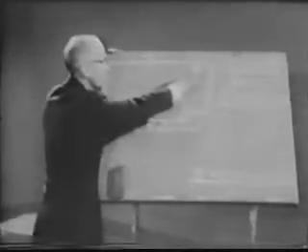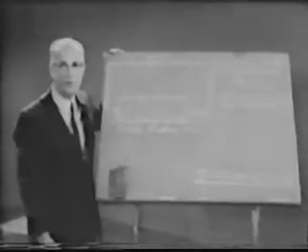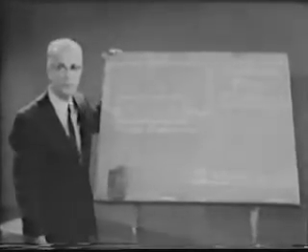The sample of germanium, which I have mounted, is quite similar to one which Bill Shockley and I used in an experiment at Bell Telephone Laboratories in 1949. The experiment demonstrated vividly, for the first time, the importance of minority carriers in semiconductors and their principal dynamical features, namely drift, diffusion, and recombination. Drift, diffusion, and recombination can be demonstrated and measured in 3 experiments that we shall show.